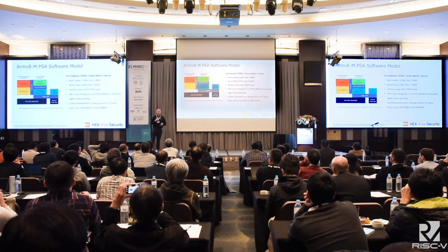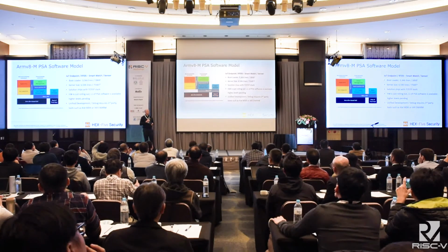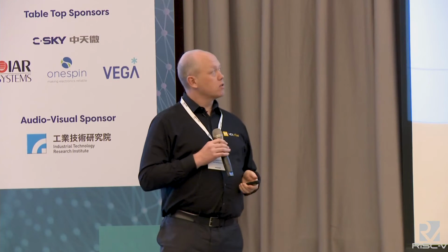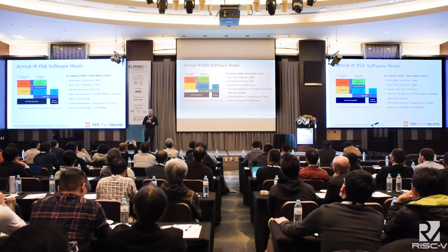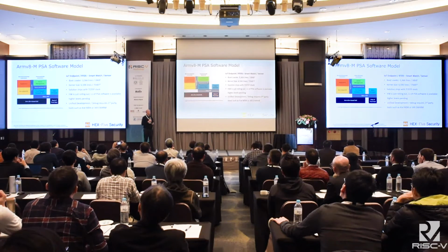We've got a bootloader here that's about 38 kilobytes in size, about 3,400 lines of C code, and a kernel that's about double that in size. What that means is you're consuming 64-ish kilobytes of SRAM before you actually get any user code onto this device. So it's difficult in a very low-cost microcontroller to deploy this without driving the price point up quite considerably. The solution ships with a TCP/IP stack whether you need it or not. It's part of the solution that comes with ARM.